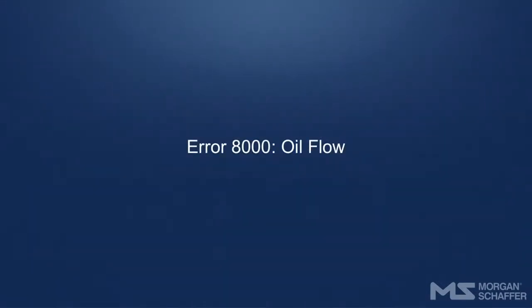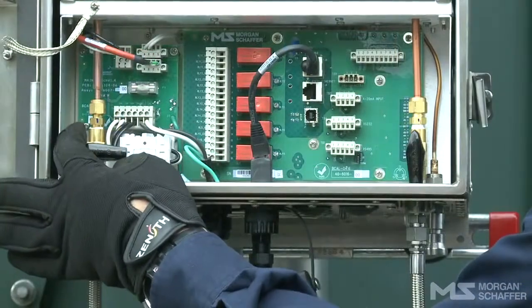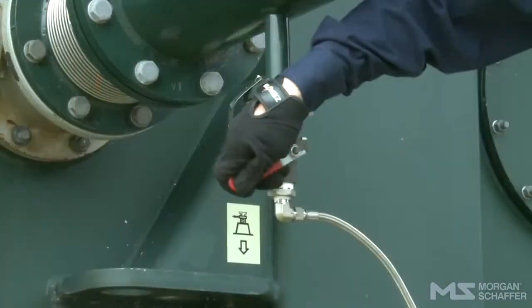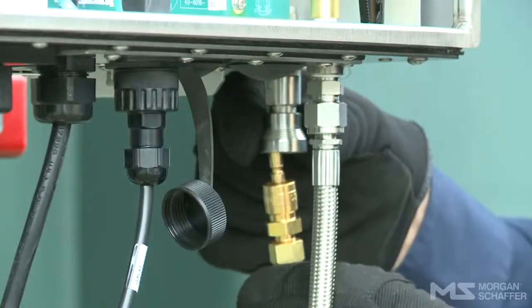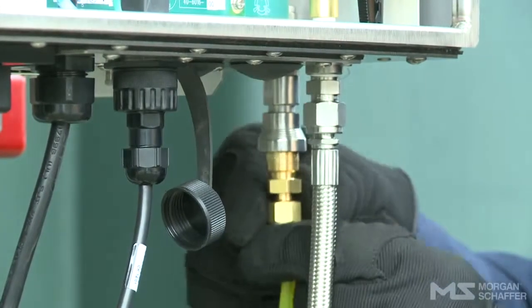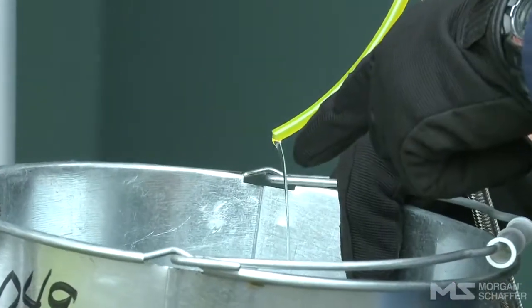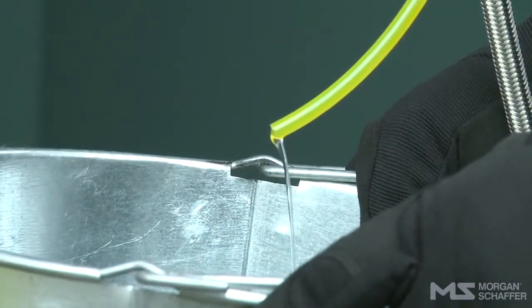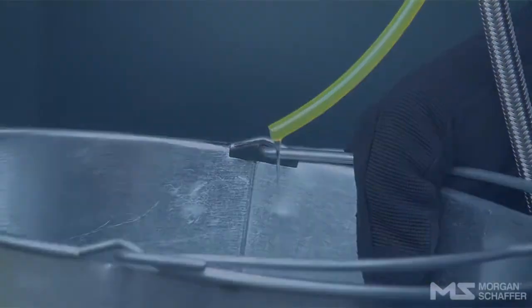Error 8000. Oil flow. This error occurs when the oil flow falls below a predefined level. Check that all valves are open, transformer and Calisto. Take an oil sample using the Quick Connect oil sampling tube and check the oil's viscosity. If these items are in order, please contact Morgan Schaefer for assistance.